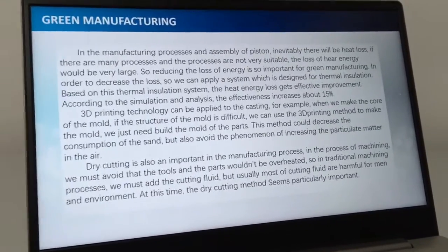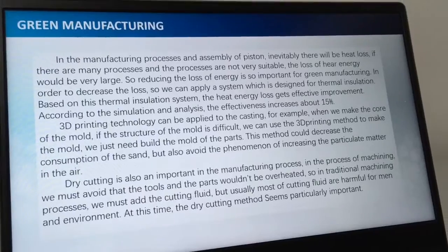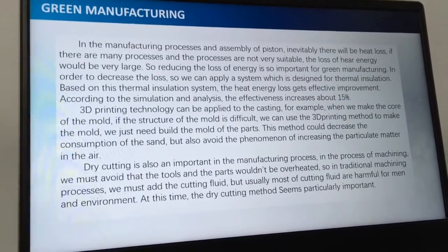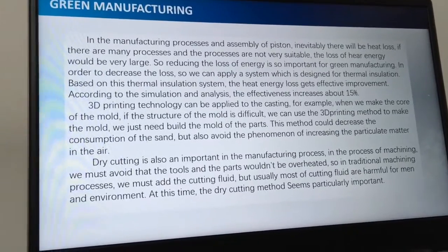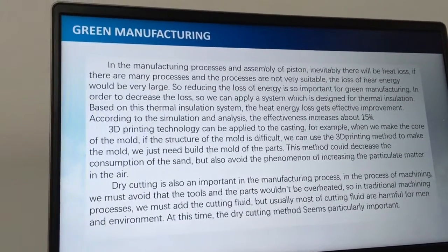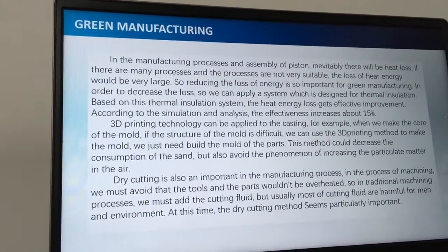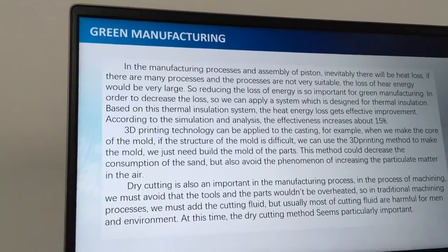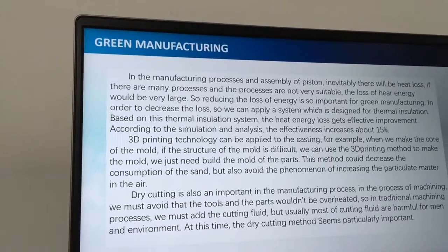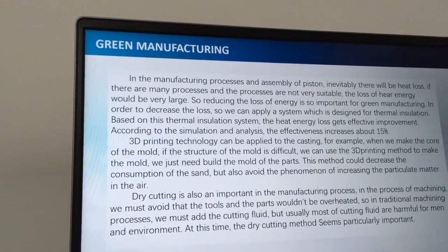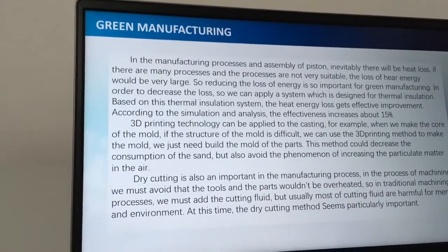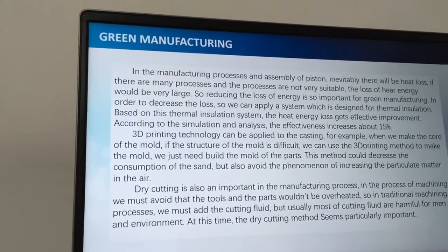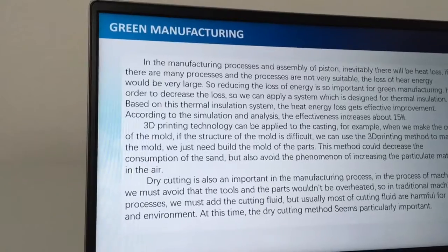Dry cutting is so important in the manufacturing process too. In the machining process, we must avoid the tools and the parts being overheated. So in the traditional machining process, we must add cutting fluid, but most of the cutting fluid is harmful for humans and the environment. At this time, the dry cutting method seems particularly important.